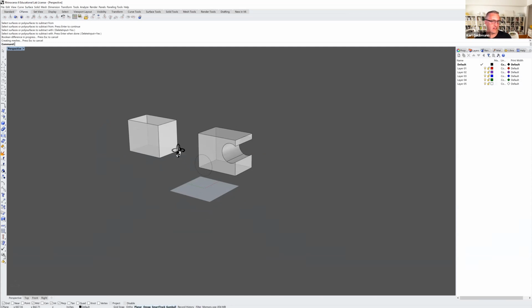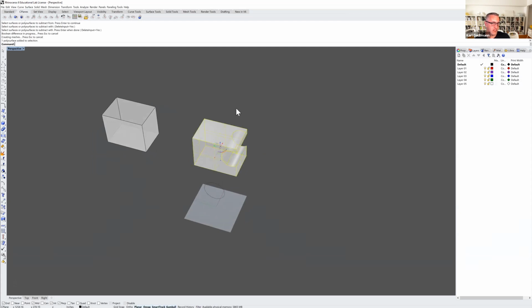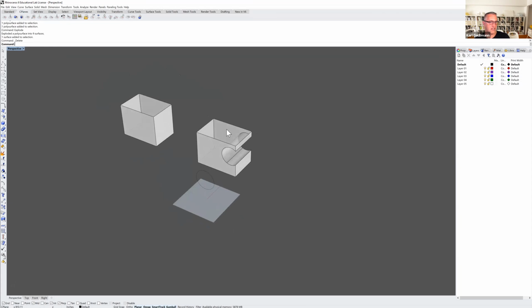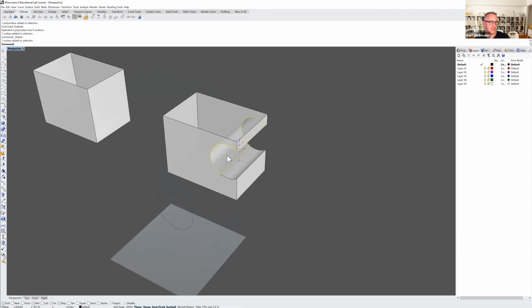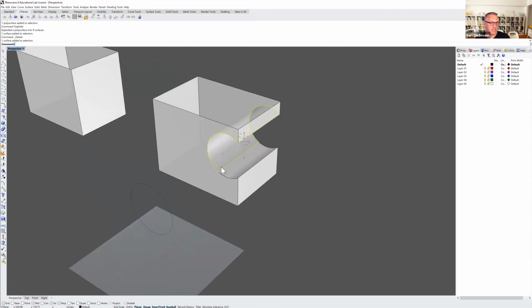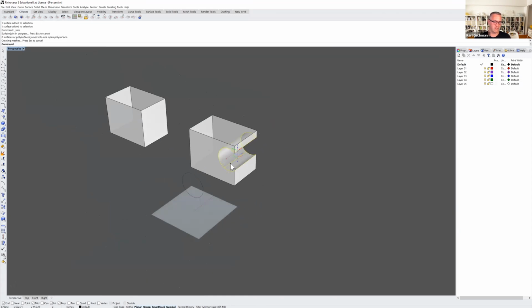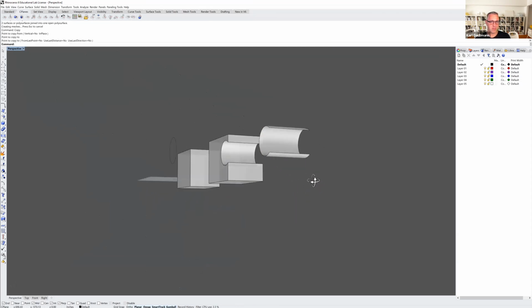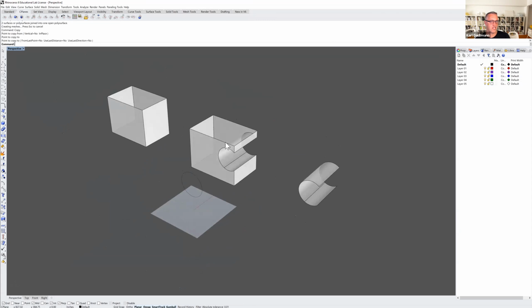So this is the difference now, right? We can explode this surface, and we can always come back, but I'll type explode. Now we can delete that top face, and now we can work on any of these as separate surfaces. And even this we can see, because the cylinder was made probably out of a couple of parts, this could be joined back together. We could copy this and even just have that part off to the side. If we want, right, these are all individual faces now.